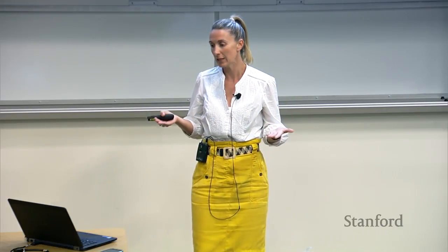So remember, we are in an adaptive system. And this is what is difficult, because you need then to detect a voltage drop in less than 2 cycles and then be able to feed back the information to improve the performances.